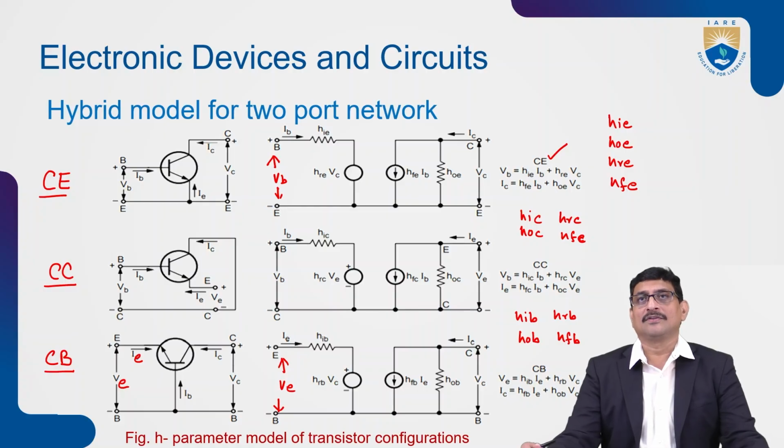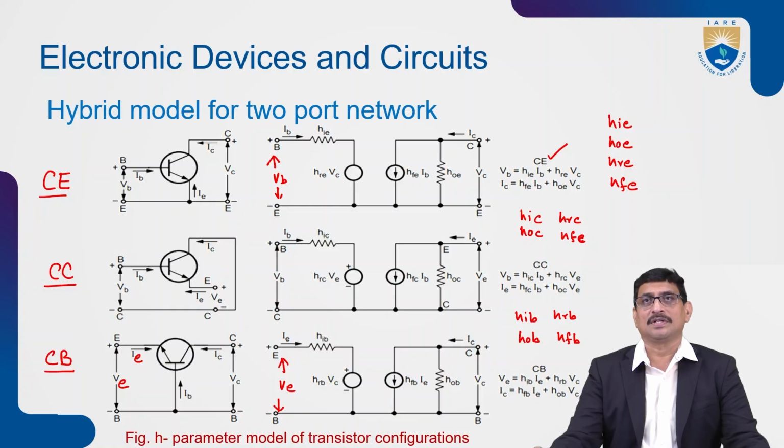Again, to get faithful amplification, we saw how the operating point is to be chosen on the DC load line, and then the transistor analysis as an amplifier analysis. To do that, the transistor should be modeled with the H parameters, and we saw why we use an H parameter model for small signal analysis of transistor amplifiers, and what its advantages are.